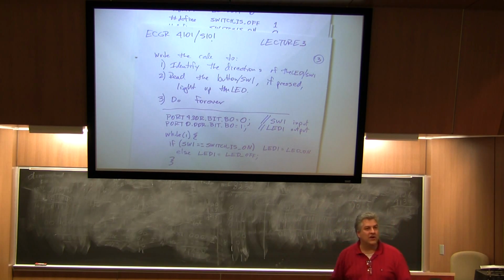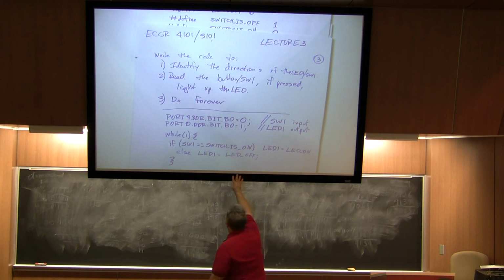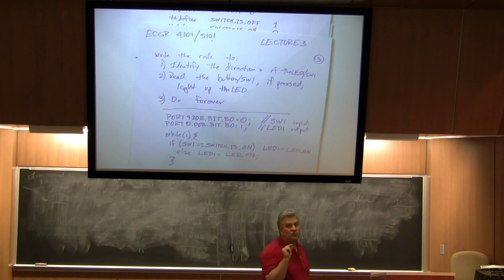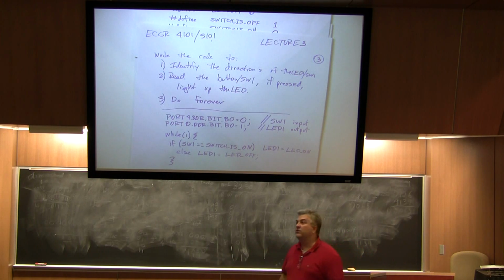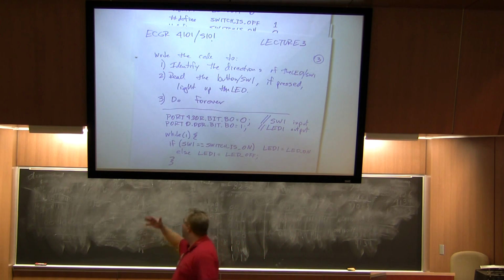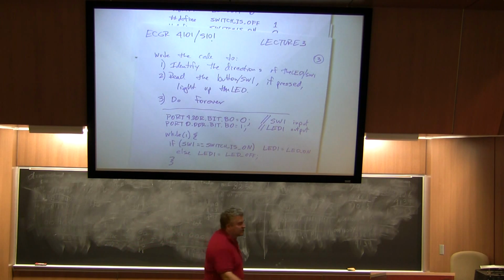This is something that you're going to be expected to do lots of in this class, all right? To understand all aspects of this. Notice I'm starting to use macros extensively. Macros make your code more readable, but you have to set it up correctly at the beginning. We've done this for you. The Renaissance board comes with a lot of these macros already set. The pound defines are already done. There's examples of them all throughout the book.